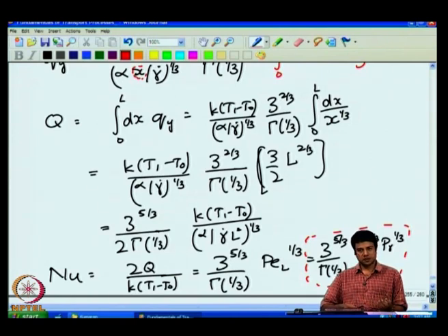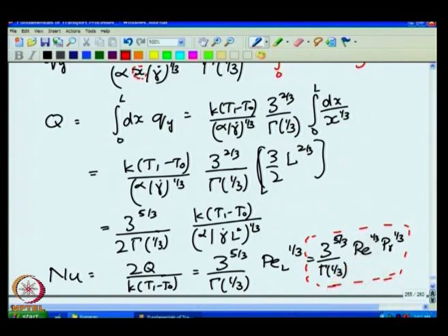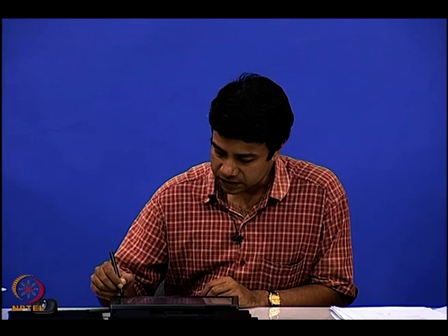There are some constants of course, but in the limit as the Peclet number becomes large, the heat flux has to be proportional to the difference in temperature divided by the boundary layer thickness. That heat flux goes as Pe power plus 1/3 because the length scale is going as Pe power minus 1/3. Okay. And once I use that condition, I can then derive an expression for the Nusselt number in terms of the Peclet number or the Reynolds number and Prandtl number.